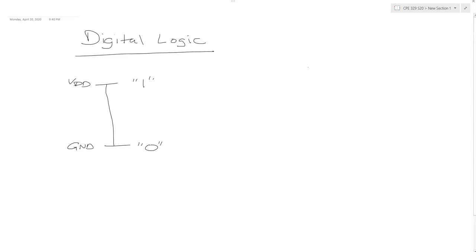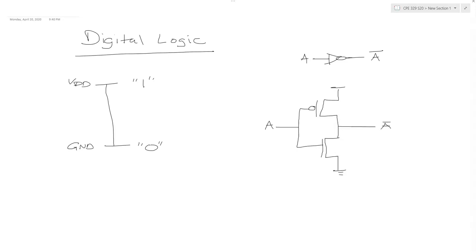And a simple circuit we can use to represent CMOS logic is something you've all seen before, which is an inverter. The CMOS inverter is implemented with two MOSFETs, one PMOS and one NMOS transistor, with the gates tied together and connected to the input, and the output coming from the net between the transistors. So let's assume our VDD is 3.3 volts, which is a common supply voltage in what we have for the MSP432, at least one of the configurations.